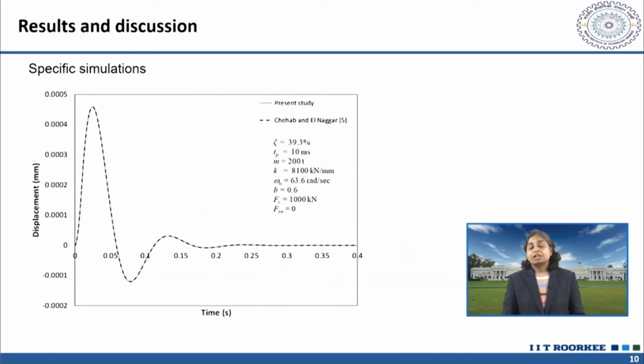We took one study which was conducted by Chehab and Elnagar. In this study, the foundation system was subjected to different types of pulse loading, and they used the Laplace transformation to get the time displacement history.